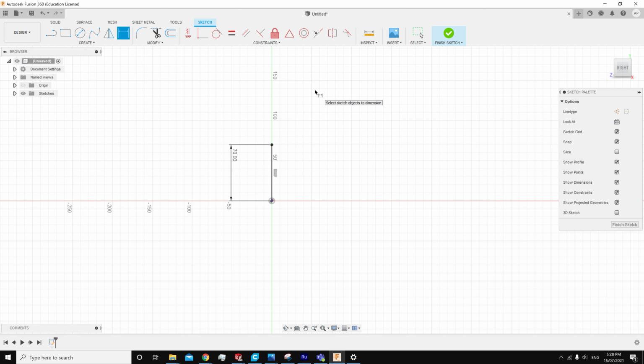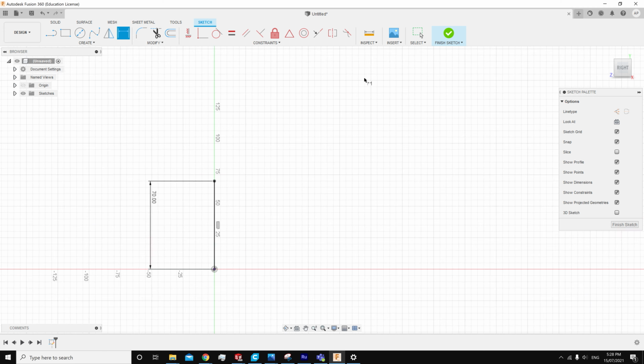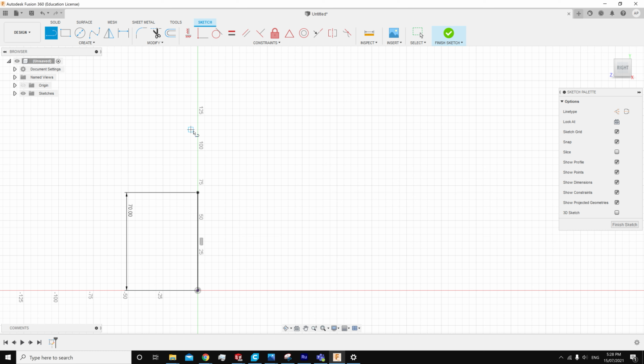If it's less than 70, it becomes really flexible. And for some designs, 70 millimeters would not be suitable at all. 70 millimeters is okay in this circumstance because the legs are actually being supported at the base by the other legs, which is taking a lot of the stress off them. Otherwise, you would find that it would be quite flexible. So if, for example, you made the bear chair with legs which were 70 millimeters wide, then it would be quite flexible. So if you were sitting on it and you sort of twisted your body around, you'd be able to feel the legs flexing.